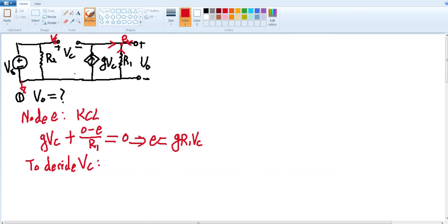what we can do is we will look at the two terminal potential, plus and minus terminals. For the plus one, we already decide its electric potential is Vs. Now what about minus? Previously, we learned that this minus terminal is connected to this whole line. So its electric potential is also E. So now we have this relationship. Vs minus E is equal to Vc.